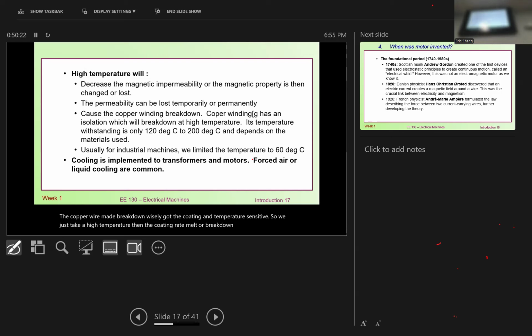If you check the copper wire in any data book, they will tell you about the operating temperature. Most of this wire is rated 120 degrees C. So if you measure the motor at 80 degrees C externally, internally it may be even higher. So 80 degrees C is really the upper limit. I think I will try to control it at 60 degrees C.